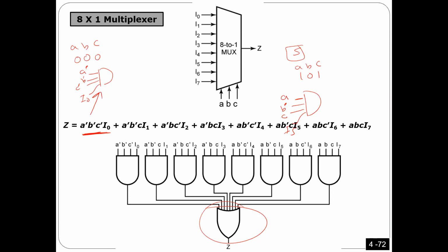So for every min term, we have one term here. This is for 0, this is the min term for 1. Very simple. If the input is 1, the three bits become 1, 1, 1, and all other terms should be 0. For sure at least one input of each of them is 0, so all of them are 0. When this one is 1, 1, 1, the output is going to be I1. So all of them are the same. Any questions?